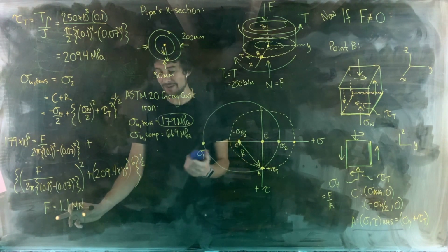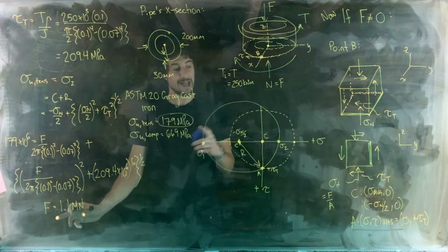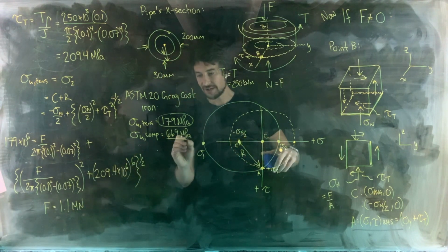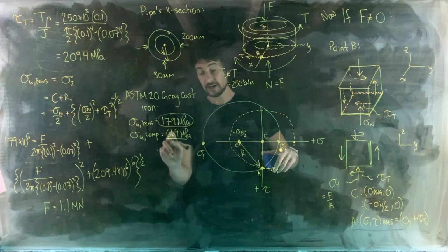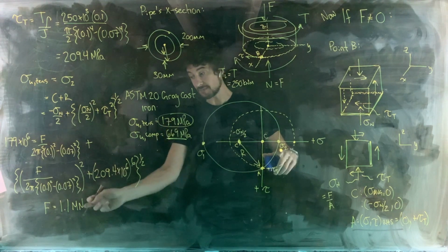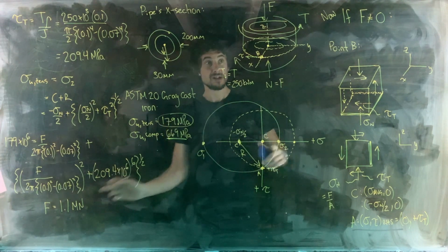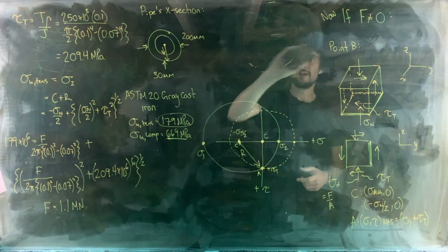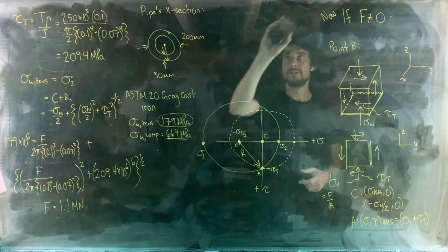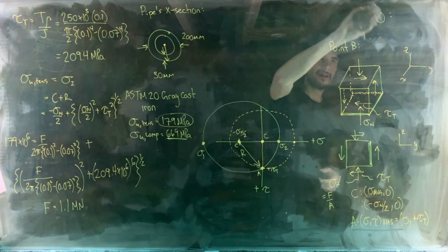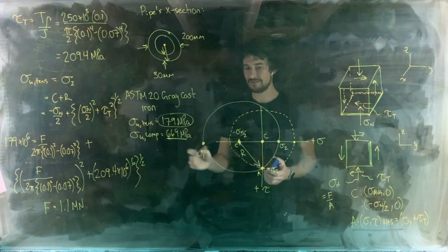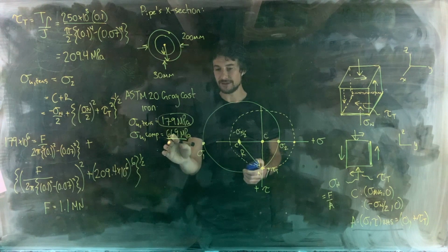So if we indeed have to apply that much force to reduce the tensile stress, have we actually exceeded the compressive stress? Compressive stress is a lot bigger than tensile stress, but that's a lot of compressive force, right? So let's just do a double check there to make sure that the compressive strength of the pipe hasn't been exceeded.